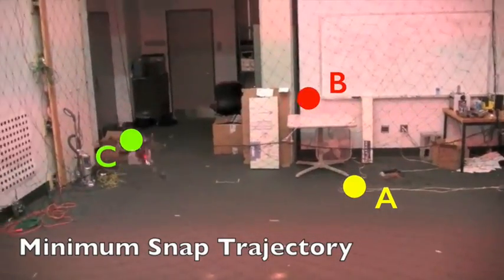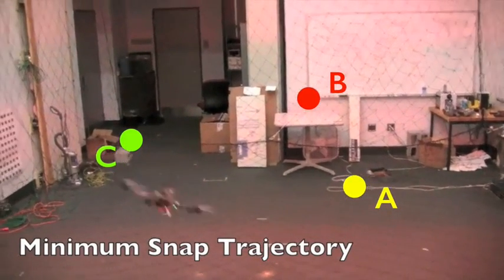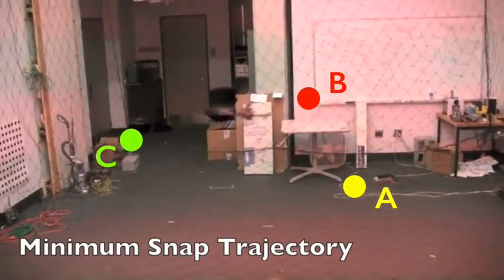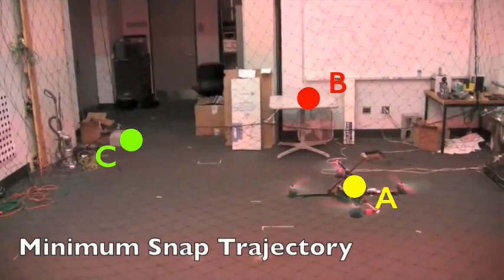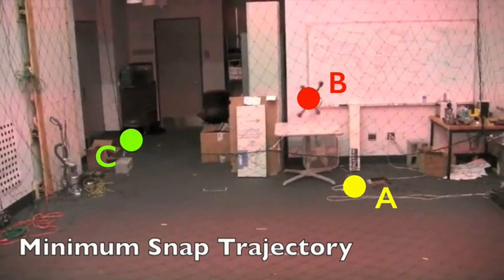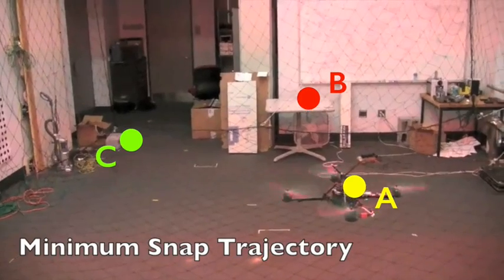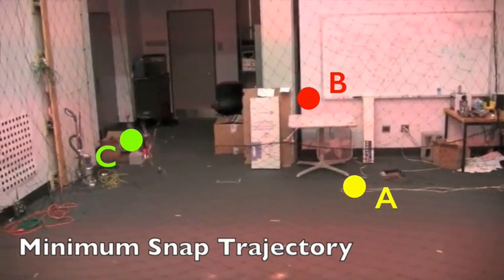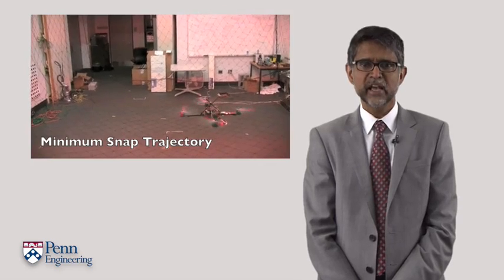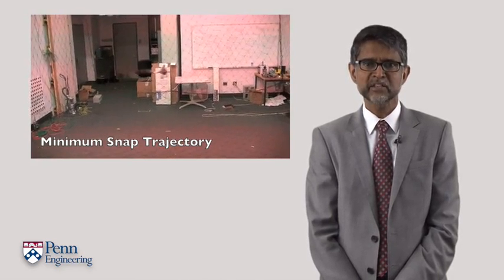So this trajectory is generated in the flat space consisting of the flat outputs without specific knowledge of the dynamics. But because these trajectories are smooth, they can be automatically transformed into trajectories that are realistic, trajectories that can be executed by a real robot. This reduces the motion planning problem to a problem in computational geometry. If we know how to synthesize smooth curves going through specified waypoints, a subject that we've already addressed in the past, we can easily transform these curves into dynamically feasible trajectories. Trajectories that our nonlinear controller can execute faithfully.